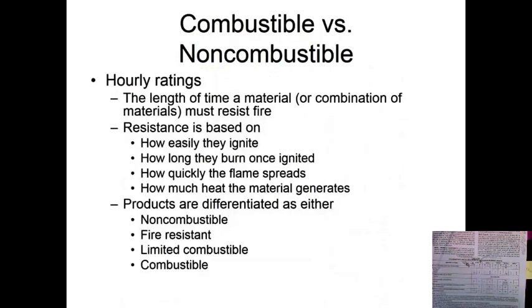Okay, so combustible versus non-combustible. When we look at it, it's the length of time a material has to be resistant to fire. Resistance is based on how easily they ignite, how long they burn once ignited, how quickly the flame spreads, and how much heat the material generates. Products are differentiated as either non-combustible, fire-resistant, limited combustible, or combustible.